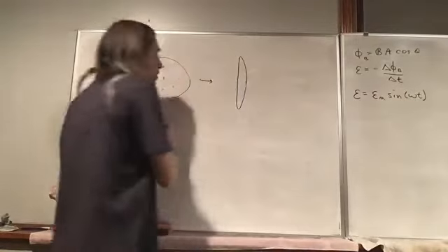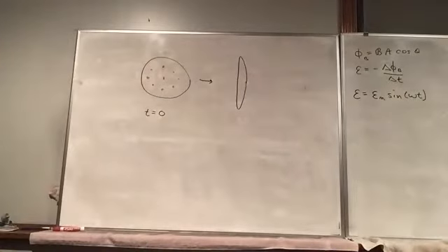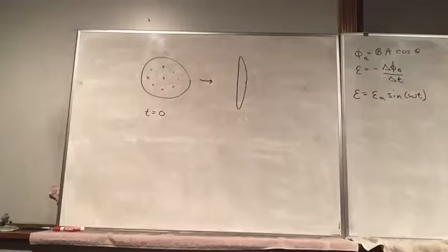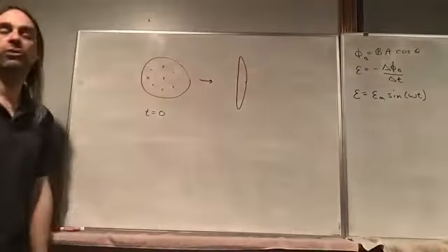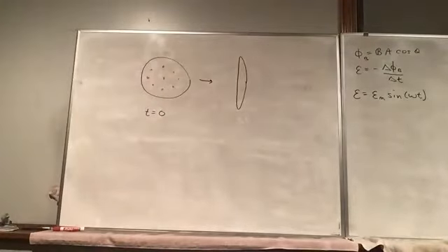So if you rotate the coil with an angular frequency omega, the EMF would be described by a sine function. And again, that's what you get in your outlet. You have alternating current. You have a peak voltage of about 170 volts, and that's oscillating up and down.